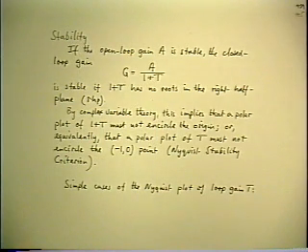You might say that's not much of an assumption, because if by definition it doesn't have any feedback, how could it be unstable? Well, that's true, but you have to remember that there's all sorts of feedback effects which are inherent in your amplifier that you may not have put there on purpose, because there's things that you can't control.